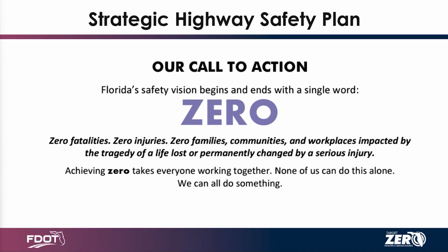So everybody knows the three ways to prevent lane departure, right? Who wants to name it? All right, short of any volunteers, just recapping. It's that safe system approach, like layers of defense. So we're keeping them in their lane, right? And we have the countermeasures to do that, whether it's high friction surface treatment, appropriate superelevation, making sure that we have drainage, a good cross slope, our shoulders aren't built up, the water can get off the roadway, rumble striping, better signs, right? So we're keeping them in the roadway.